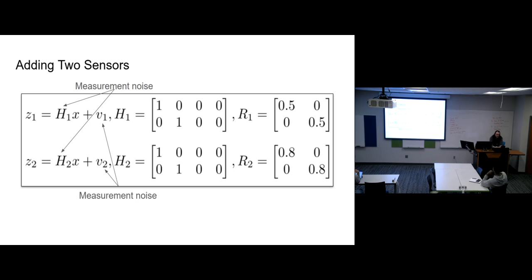Because all it takes is something hanging up there, and then your temperature sensor is responding slow, and now your speed sensor is not keeping up with what you actually need. Especially on systems where you might be sampling your temperature at 1 hertz, but your encoder at 40 hertz, right? Or something like that.